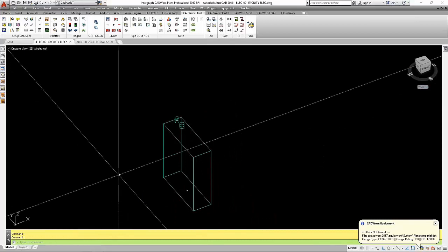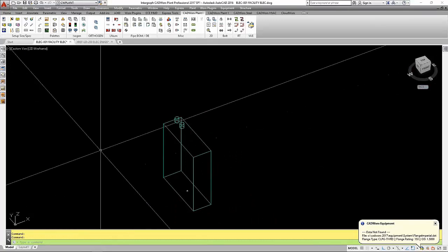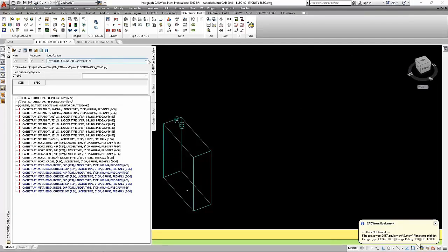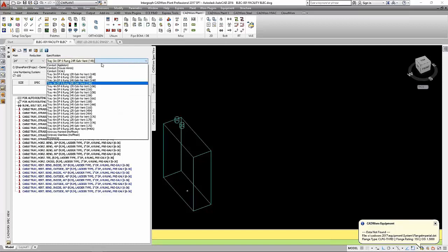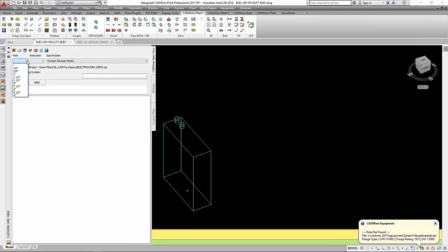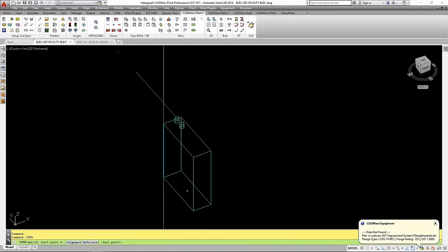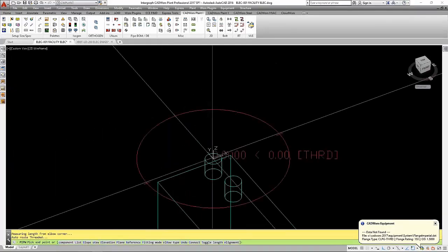All right, let me get set here for drawing pipe. No, I mean Conduit. Because it's CADWorx, because it's pipe, we can use the spec editor here and just pick the spec we want to use. Now ELECTROWorx comes with a bunch of specs, Appleton, Crouse-Hinds, all these conduit type components, wireway components, cable tray components. So we pick a size here, 1.5 inches. I'm going to route with a 10-foot piece of conduit. I've got 20 as an optional component, so that's sitting there in blue. So I'm going to run with 10-foot conduit.